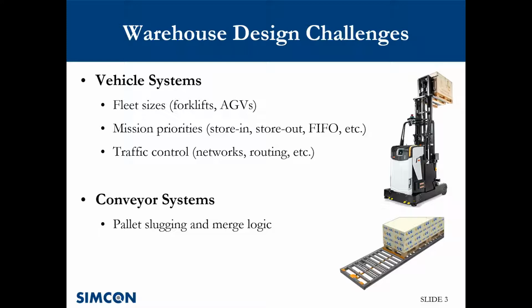For the vehicle systems, the most important thing you need to figure out is how many actual AGVs you need. You want to be able to keep up with demand, but you also don't want to waste money on a bunch of extra AGVs that you don't need. That's something that simulation can really help out with a lot.